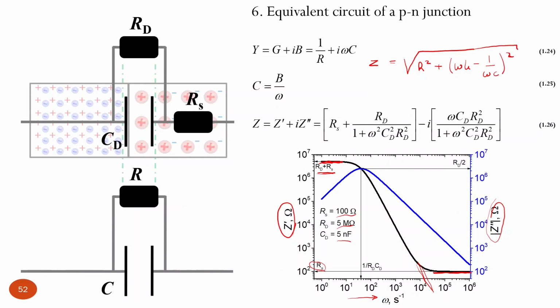So you see that because of phase shift between voltage drop over inductor and capacitor, we have here plus and here minus. So when we consider phase shift between current and voltage, we have this minus next to contribution of a capacitive reactance.